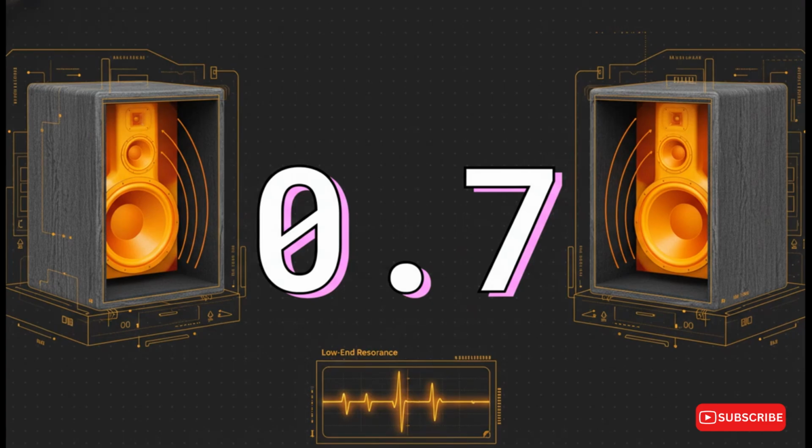Now, take a look at the exact number shown here, 0.7. In acoustic engineering, this QTC alignment factor represents the absolute laboratory ideal for a sealed cabinet system. Hitting this number provides the best possible combination of an even frequency response and deep extended bass. If you mess with the internal volume and that number creeps up above 0.7, well, you start getting this artificial hump in the bass response, a boomy, muddy quality that completely disrupts clinical accuracy.